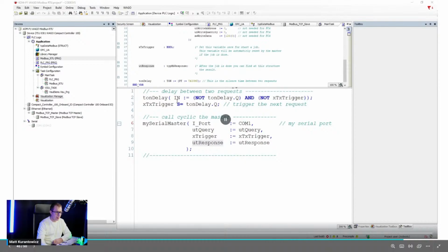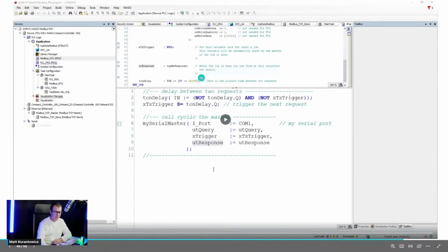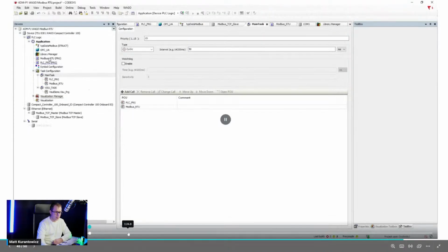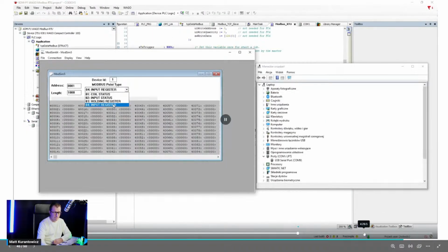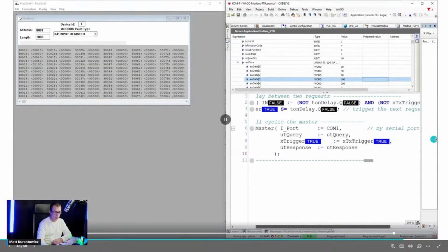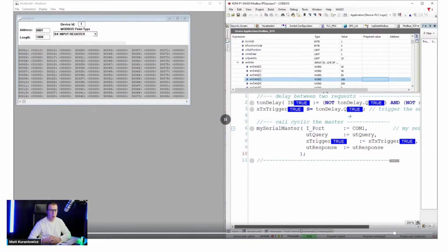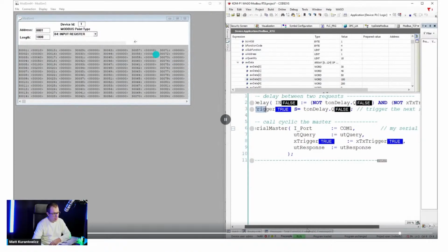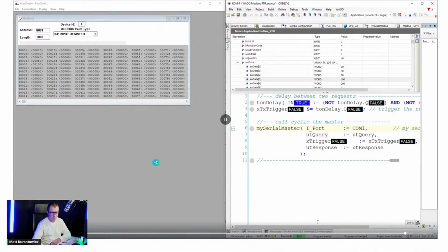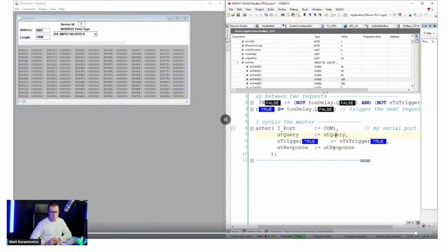Here we have another example, but in that case, we have a program for Modbus RTU communication, and we use a specific function block for Codesys. And here we have a simulation for Modbus slave. Maybe I will show you the communication. And look at that. Here I communicate a Wago PLC using Modbus RTU with my Modbus slave. And we have here a query and a timer. Each second, we send a request using Modbus master to the network, to our slaves.